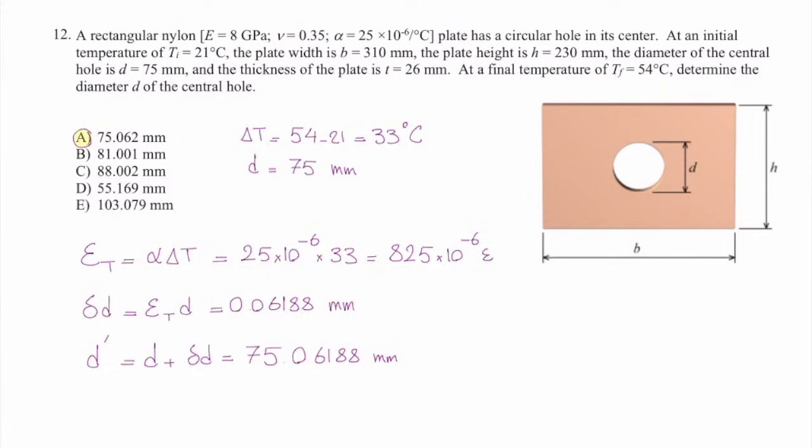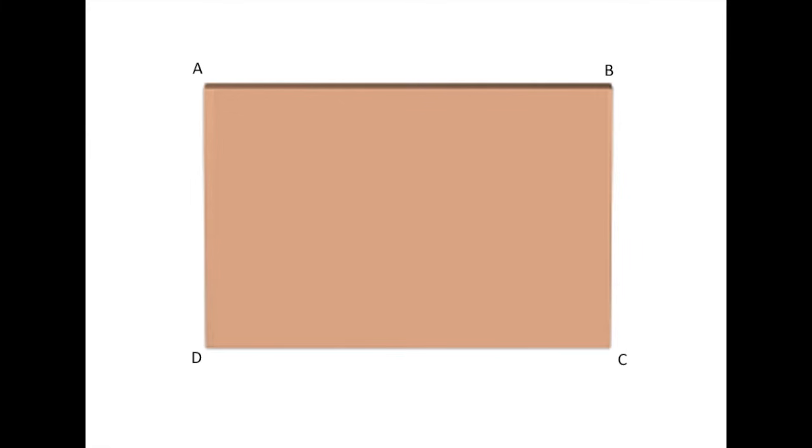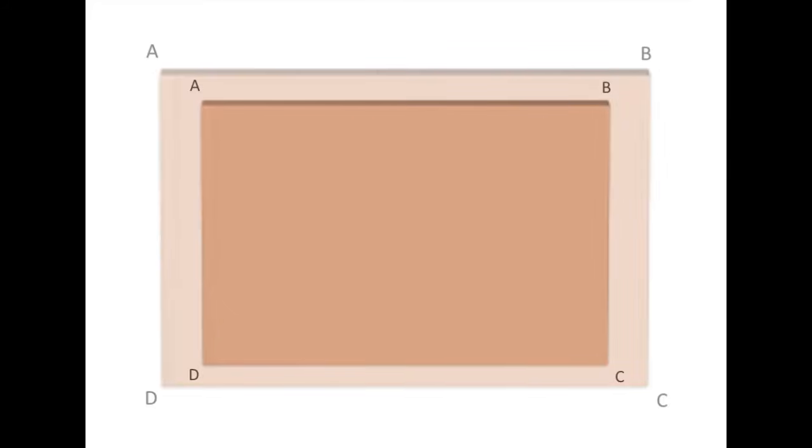Questions? Yes, sir. Okay, it's a good question. Can I ask you to repeat your question again here? So if there's material on the top and bottom of a circular hole, why doesn't the diameter of the hole reduce as the material on top and bottom expands? Okay, so consider one simple plate there. What happens if we increase the temperature in that plate? The entire plate gets larger, correct?